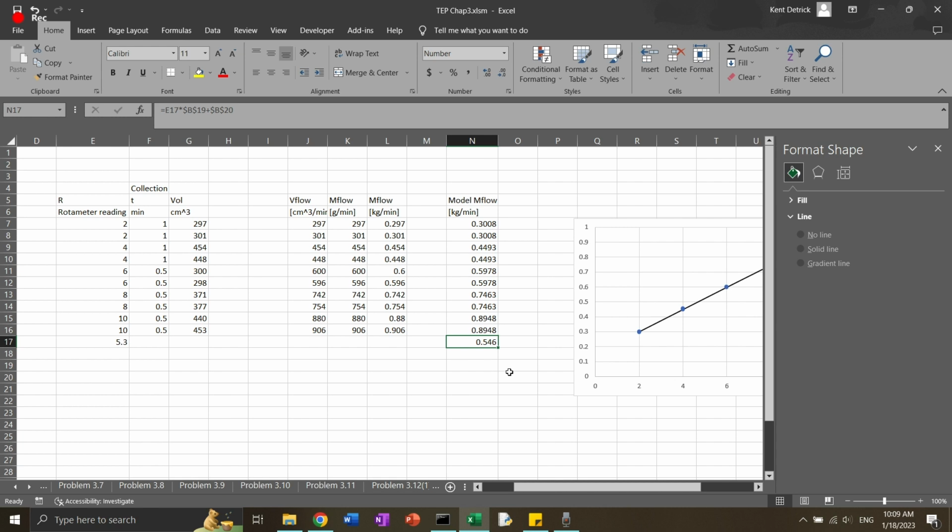For example, if a single measurement of Y yields a value Y measured, then there is a 95% probability that the true value of Y falls within 95% confidence limits, where Y measured plus or minus 1.74 times the mean difference between duplicates. For a measured flow rate of 610 grams per minute, estimate the 95% confidence limits on the true flow rate.